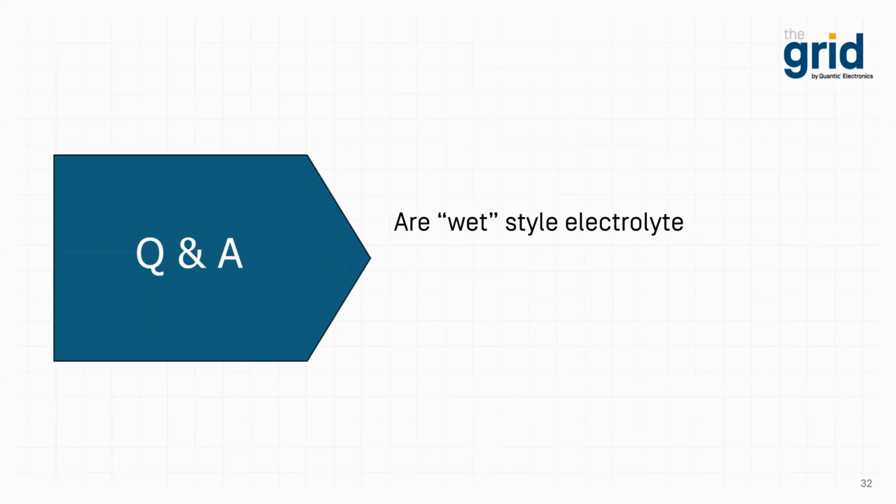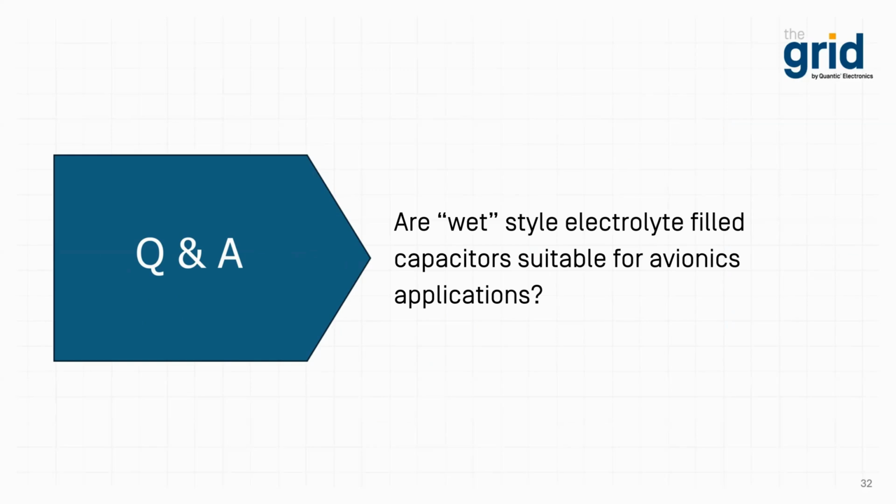The next question, are wet style electrolyte filled capacitors suitable for avionics applications? Yes, we get this quite often. There is a fear of designing these capacitors in avionics applications because if it's filled with an electrolyte, which is typically conductive and perhaps corrosive, there is a potential to leak.